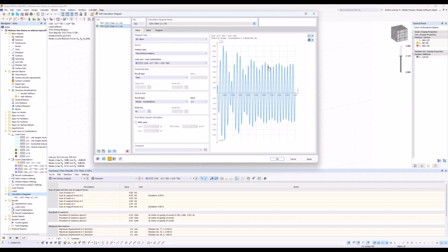That depends on you and maybe also on the stress level of the structure. But normally these bracings could be really small, because you just have normal forces in these bracings because they are hinged at the start and at the end, and therefore it is normally not necessary to use big cross sections.